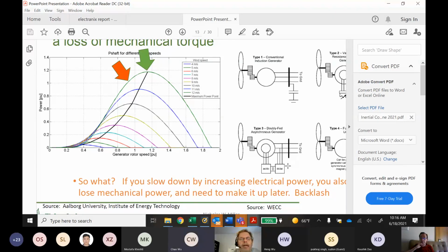Okay. Thank you. And maybe one more is about your operation, which is always under the MPPT point, yes. So if we want to do the inertial support, we can run it in a deloading operation, like over this speed, and then if you want to decrease your speed, you can enlarge your power, so it can buy more time for the power support.